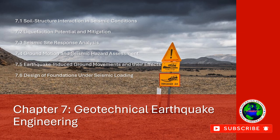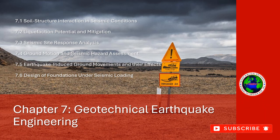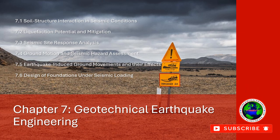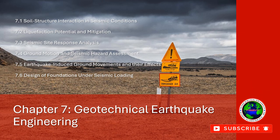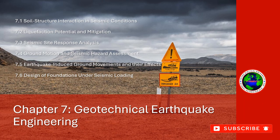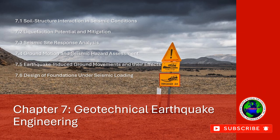Seismic settlement refers to the downward displacement of the ground during an earthquake caused by the compaction or consolidation of loose, granular soils or soft clays. This phenomenon can lead to the settling of buildings, roads, and other infrastructure. Seismic settlement is more pronounced in soft, loose, or saturated soils, which are prone to compression during strong ground shaking. 5. Liquefaction-induced ground movement.